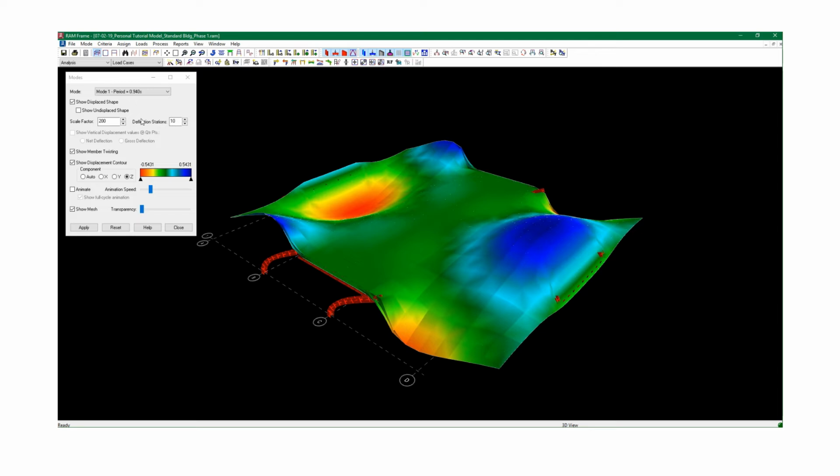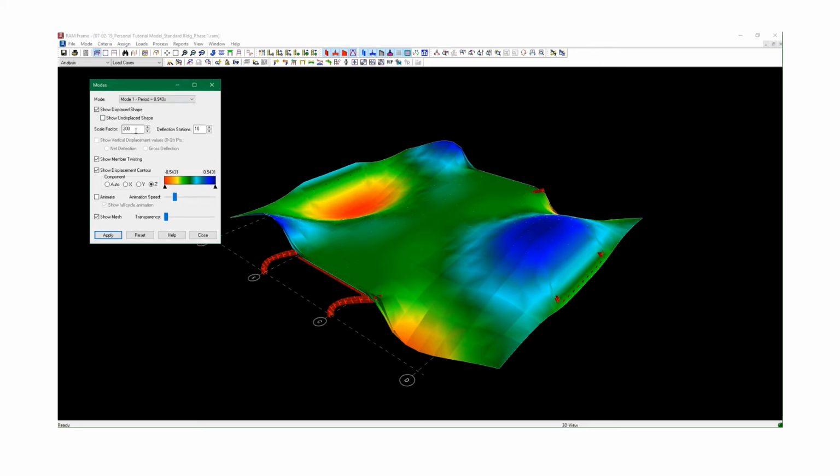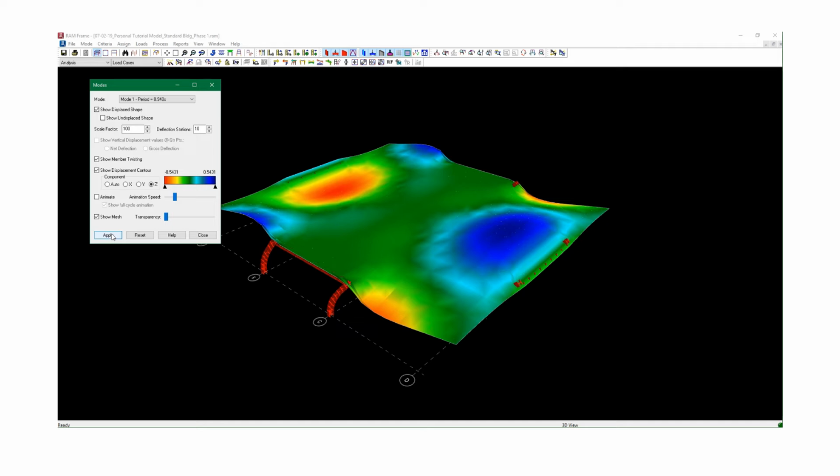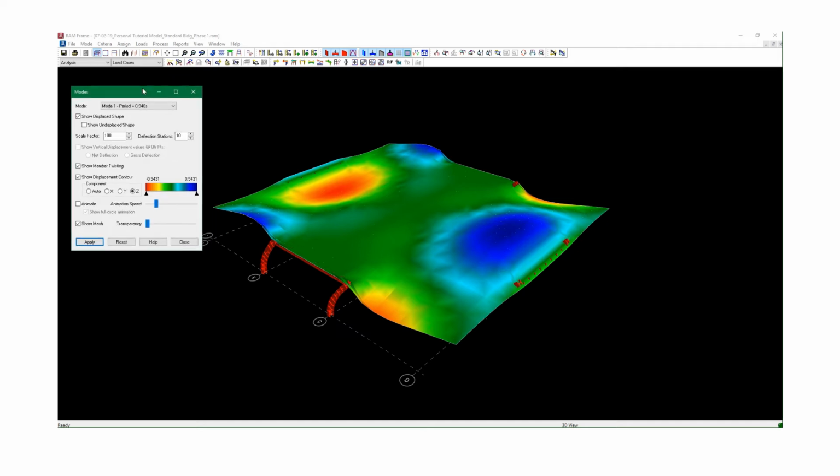You can see that you get the dialog box and it shows you a shape. You can scale it differently if you want. Apply that so that it doesn't look too distorted. I like to choose auto for these things, but the period of the structure is actually less than 1. So that means that the structure right here should be considered, I believe, rigid at this point.